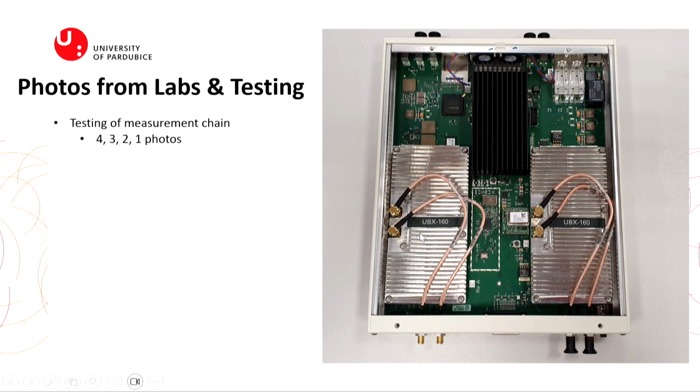And this is TXRX and TXRX, where 160 is 160 megahertz bandwidth, if I remember well. So it is a classic SDR radio, almost a digital device: the signal comes from the antenna, then some amplification, filtering and AD conversion, and from AD conversion it is just digital processing.